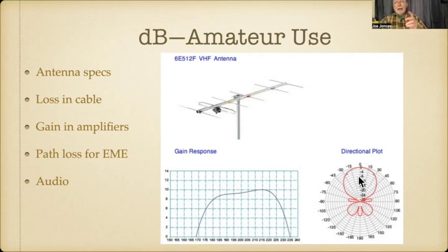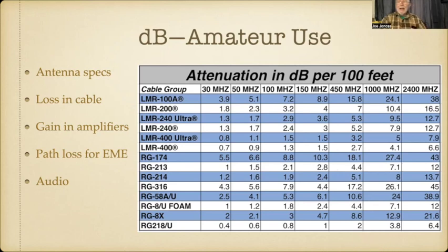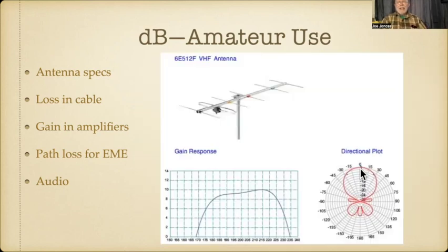And this here is an illustration of how the antenna takes the signal and reshapes its directivity. So in front of the antenna, this would be 0 dB. But according to this, at that point, that's a 10 dB gain about. Back here, if you go at this point here, this is off the back of the antenna, straight back. Back here, you take that point here and you come on around, and that's minus 20 dB.